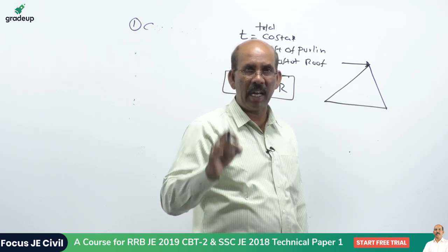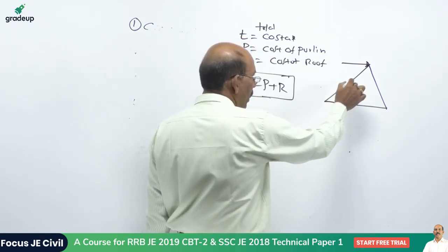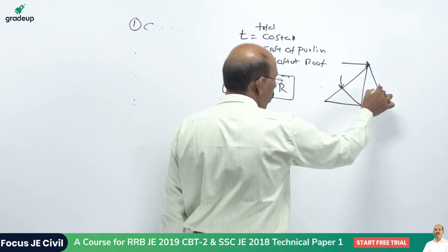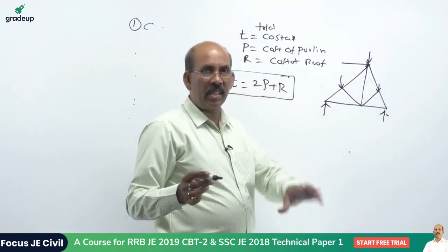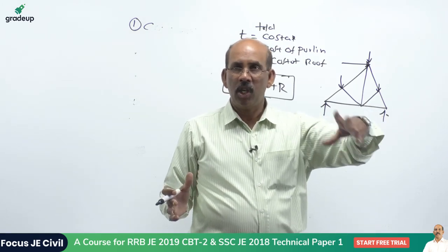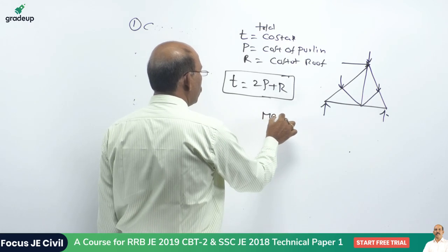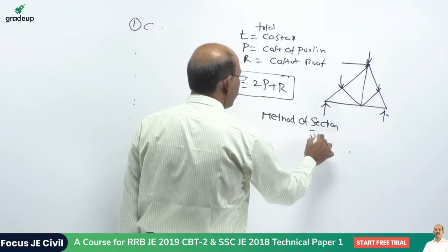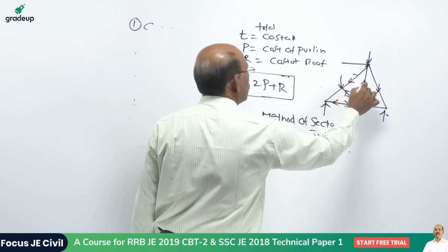And coming to the load and analysis here, for any member, as in the case of steel that you want to design, you can apply the loads at these nodal points, and these are the reactions, and various loads can be considered on our truss. Accordingly, you analyze this truss with the help of the method of sections or method of joints and determine the magnitude of the forces in the truss.